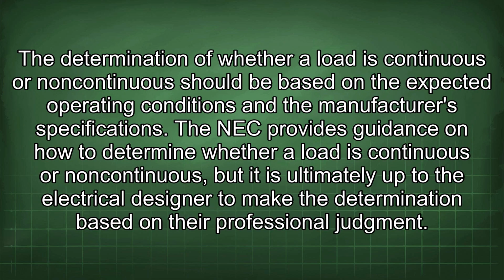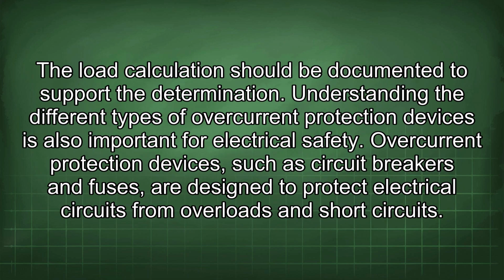The determination of whether a load is continuous or non-continuous should be based on the expected operating conditions and the manufacturer's specifications. NEC provides guidance on how to determine whether a load is continuous or non-continuous, but it is ultimately up to the electrical designer to make the determination based on their professional judgment. The load calculation should be documented to support the determination.